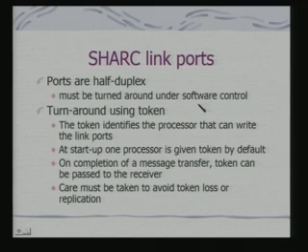Typically, a token based protocol can be used. The token identifies the processor that can write the link ports, and the token is stored in a particular memory location local to the processor. In fact, these processors are also not sharing any memory among themselves. At startup, one processor is given the token by default.